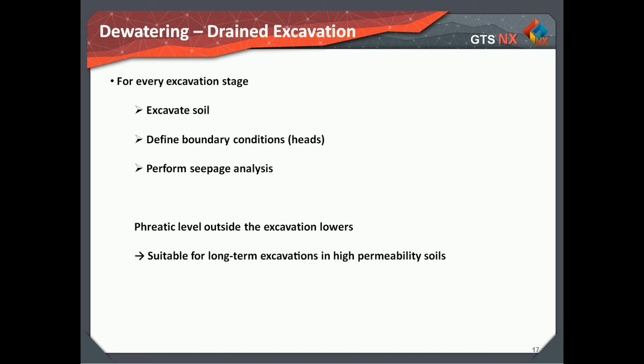In case of drained excavation, similarly for every excavation stage, firstly excavate soil and define boundary condition using the head boundary and perform flow analysis. Piezometric level outside the excavation lowers, so it's suitable for long-term excavation in high permeability soils.